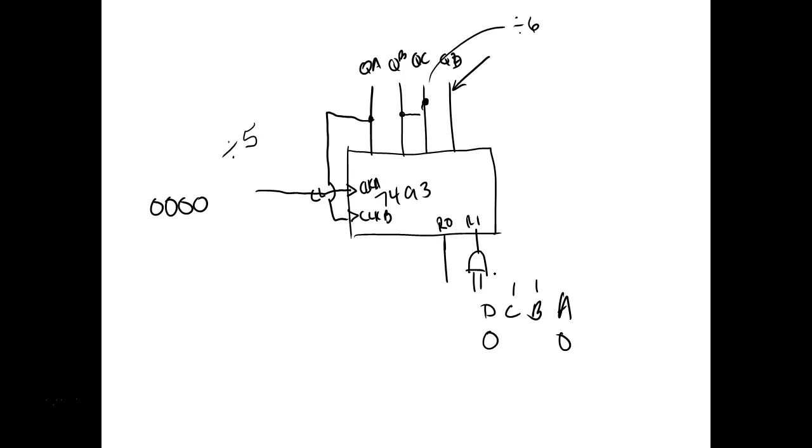I could wire it to do a divide by 2. If it's a 2, 4, 8, 16, I just use that outlet, right? So this guy right here is really, really neat. The 7490 just has the AND gate built inside of it.